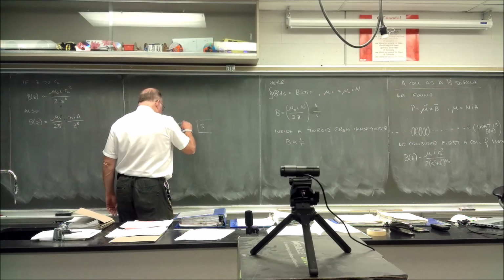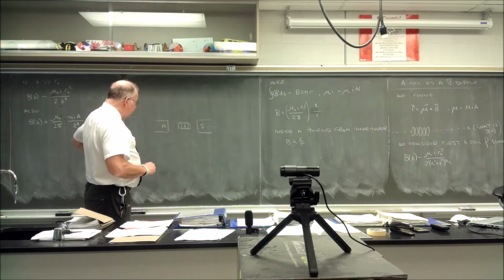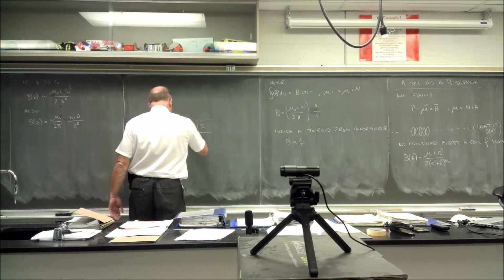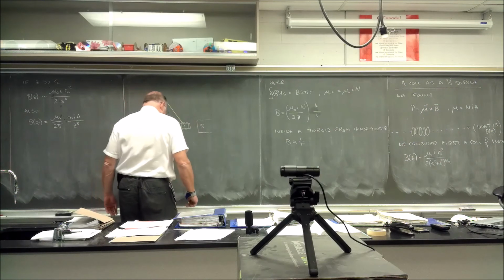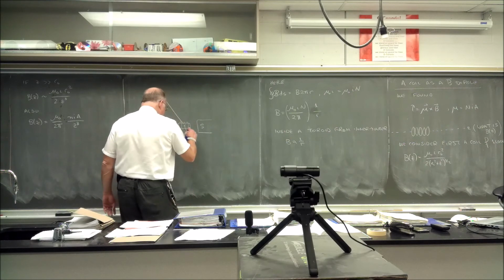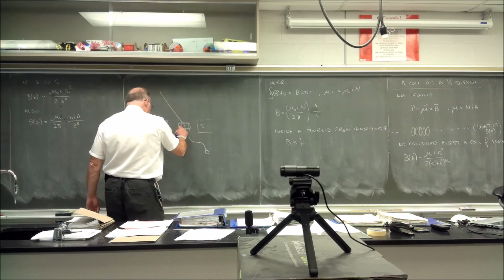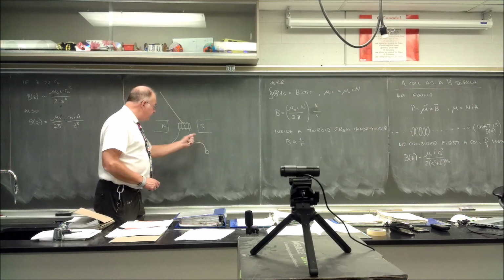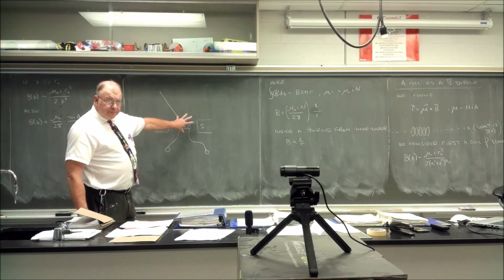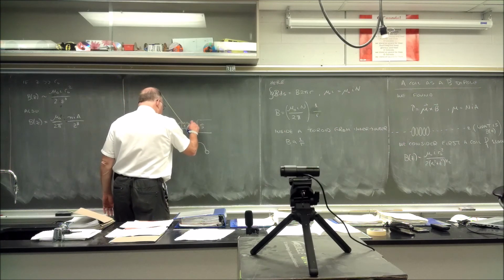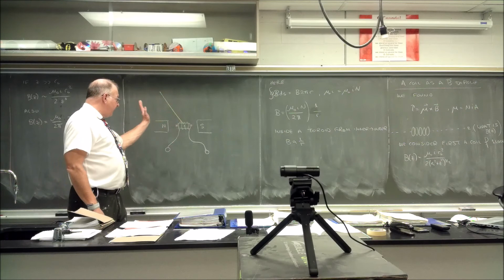And there's an axle that points out of the page, okay? So this thing can rotate like this, okay? And we'll stick on here, at some arbitrary location, a wand, and then we will connect the wire here to a terminal, and the other wire over here to another terminal. And when a current passes through, this will energize. And this is designed to energize in such a way that this will be north and this will be south if it's connected properly. If it's connected wrongly, it'll slam this way.